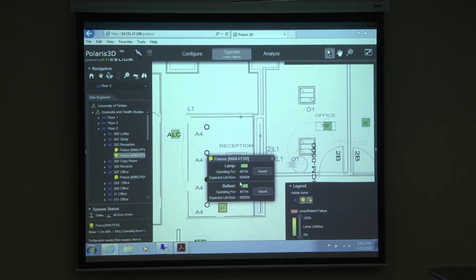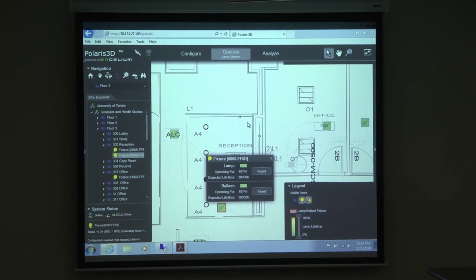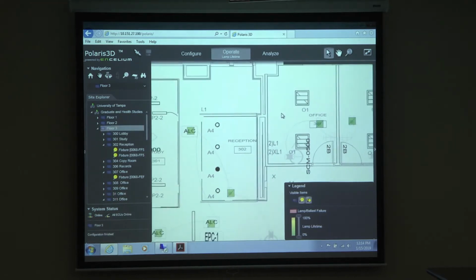And that's the downfall of this part, because the one module is doing all 4 of these devices. If one device goes and you change that one and hit reset, it resets everything, so that will skew your number a little bit. That's where our dating comes in. We would date our new fixture. We already have the running total, so we know what the system has and we know the date, and we can do our own math. We just date our install on a new one and write down where the hours are. We can guesstimate within a plus or minus of that. So we would continue our dating process without resetting the module.